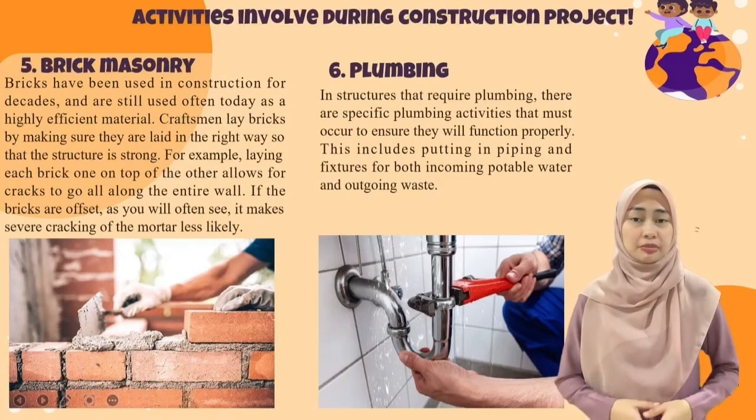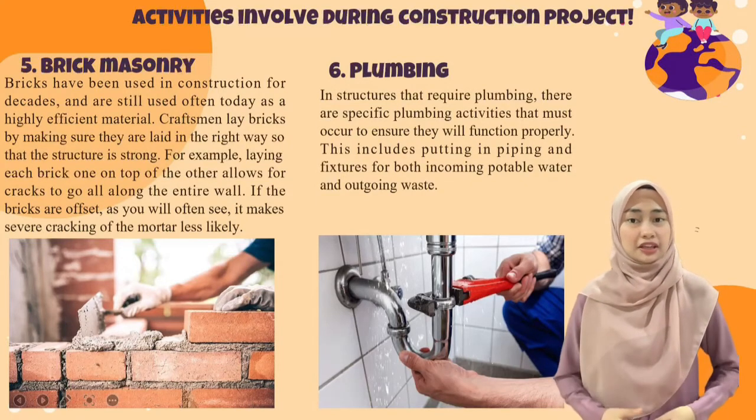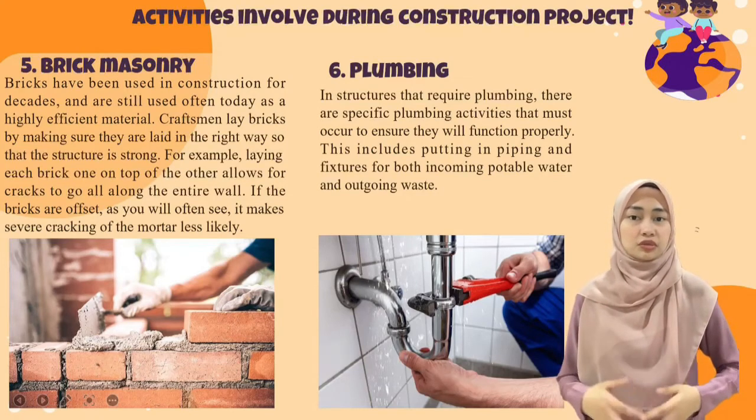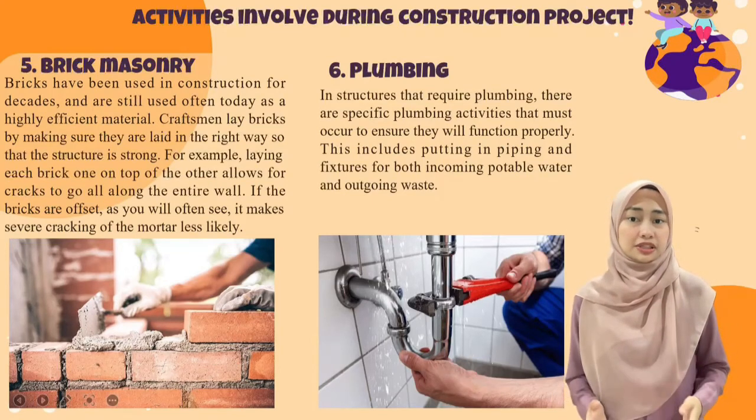Craftsmen lay bricks by making sure they are laid in the right way so that the structure is strong. For example, laying each brick one on top of the other allows cracks to go all along the entire wall. If the bricks are offset, as you will often see, it makes severe cracking of the mortar less likely.